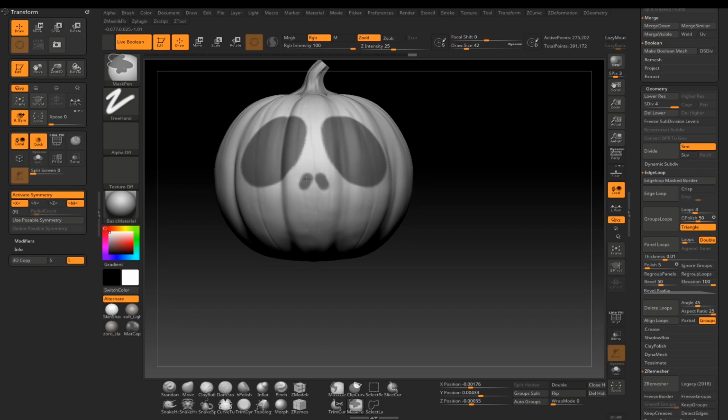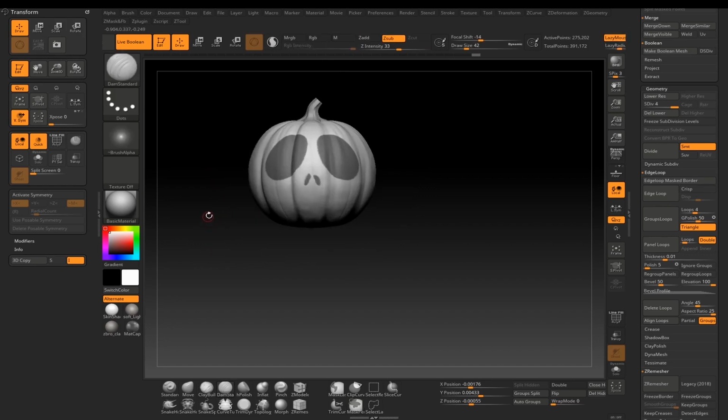All right, we make the nose with that technique. And now if you hold down the Control and the Alt key, you can subtract the mask. So it's a kind of mask eraser, or yeah, you invert the mask function again. As I said, the Alt key inverts our brush. It is true for the mask too. So I try to make the nose more asymmetrical.